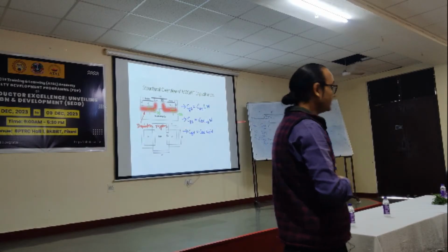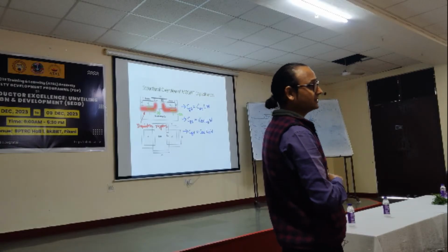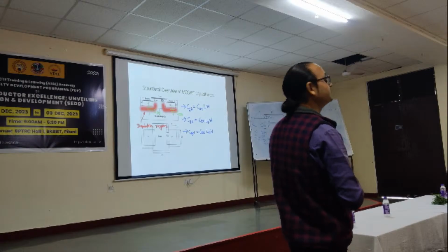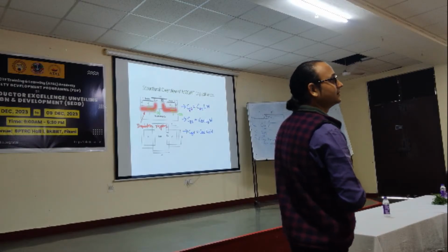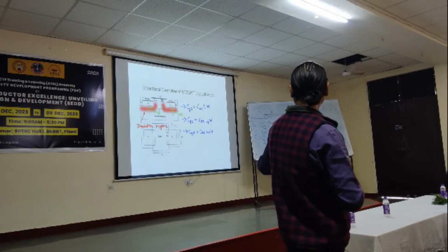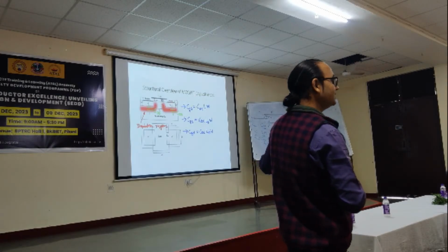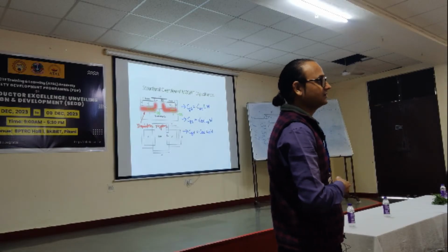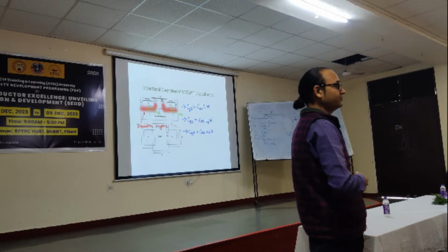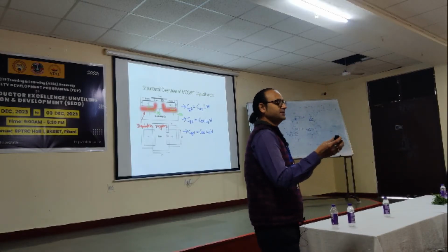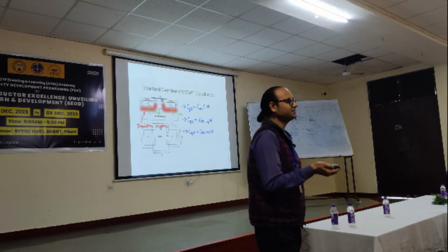That was the overlap capacitance, which we discussed earlier. This is depletion capacitance because a PN junction will be there, reverse or forward biased. In general operation, we apply positive voltage at the drain, which is N type, and ground the substrate. So obviously it is reverse biased, and these reverse biased junctions give rise to capacitances. Why are we going through this capacitance?